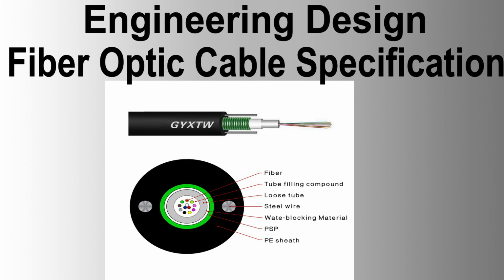Outer sheath identification. Marking. The outer sheath shall be marked with the manufacturer's name, fiber count, standard code, week and year of fabrication, progressive metric marker, customer name, project name, and project contractors. The letters shall be clearly printed by means of non-metallic paint. These requirements ensure the high performance, reliability, and durability of the fiber optic cables used in the project, aligning with international standards and project specifications.